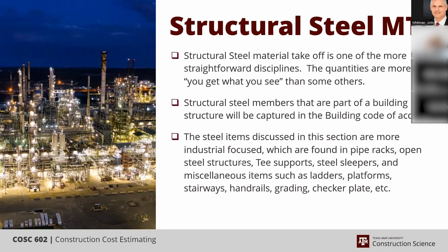It depends on how you want to approach the project and how lean you want to make your numbers as you're bidding, honestly. It goes back to, do you use 3% or 5% or 4% on your overage? 3% is pretty common, but if you look at the type of form, if it has a larger face on it and you don't put enough kickers on it, it's going to bow more than if it's shorter, tighter, or you brace it quite a bit. So it's somewhat of a judgment call. So I'm not going to fault you either way, honestly.